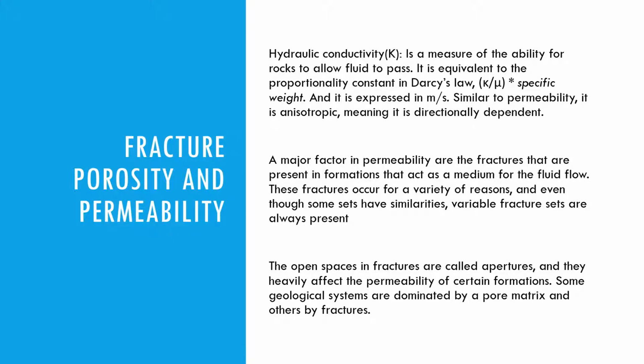Hydraulic conductivity K is the measure of the ability for rocks to allow fluid to pass. It is equivalent to the proportionality constant in Darcy's law, which is permeability over mu, which is dynamic viscosity, times the specific weight. And it's expressed in meters over second, so kind of like velocity. Similar to permeability, it is anisotropic, meaning it is directionally dependent.